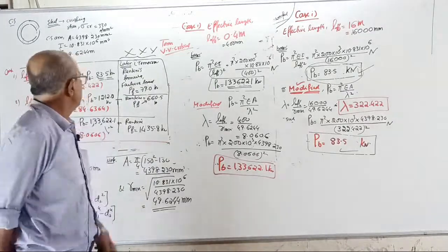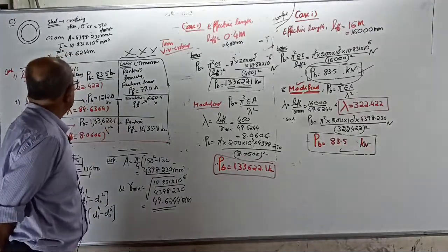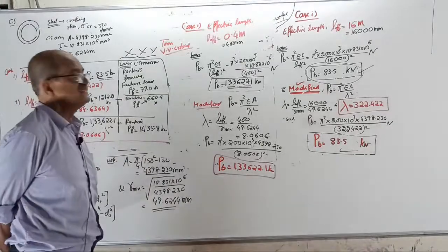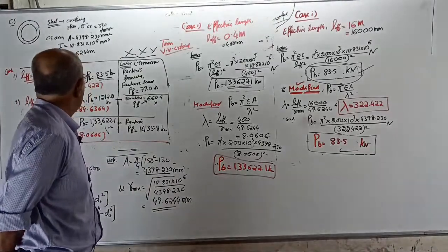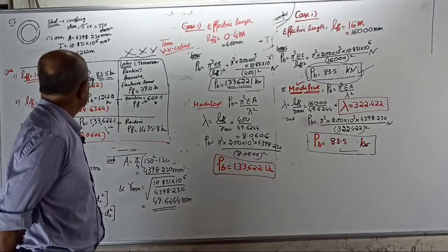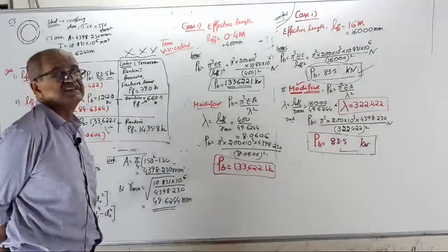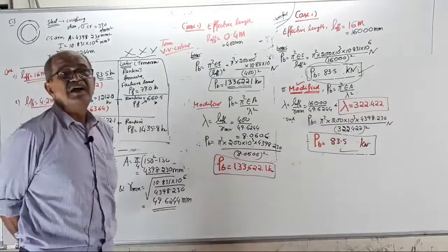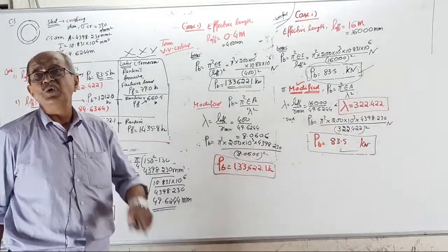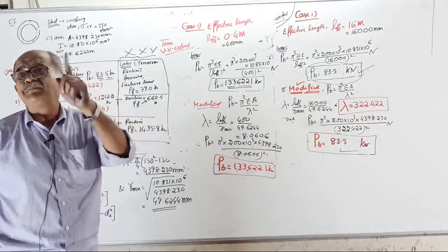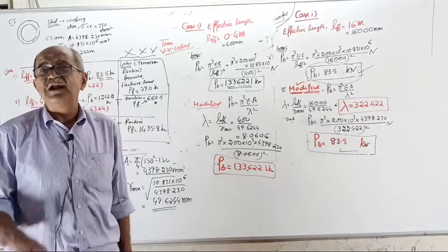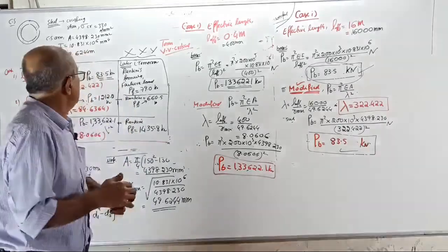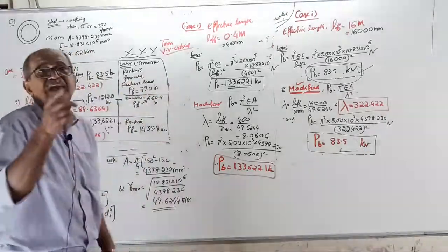Okay. Practically okay. Second one, Euler tells 1200. Rankine tells 660. Hey Euler, what is this? Rankine is telling 660. You will tell, who is Rankine? You can tell Euler, Rankine is the one who gave formula applicable for any column that is practically accepted. So Rankine is realistic formula.